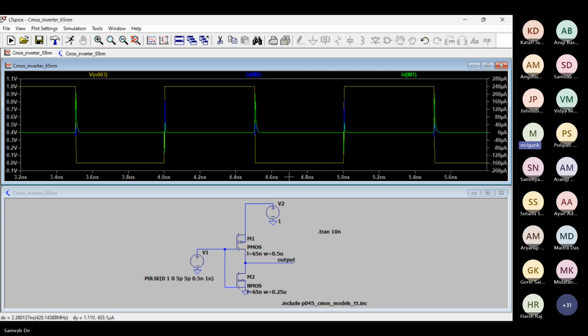That part I will have to see, because if you are only talking about the static current flow or the short circuit current, that should be from VDD to ground. That means it should be positive in the PMOS and positive in the NMOS. But if there are other current components because of charge sharing and capacitive coupling, that we have not discussed yet, that may lead to some additional component that I will discuss in the theory.